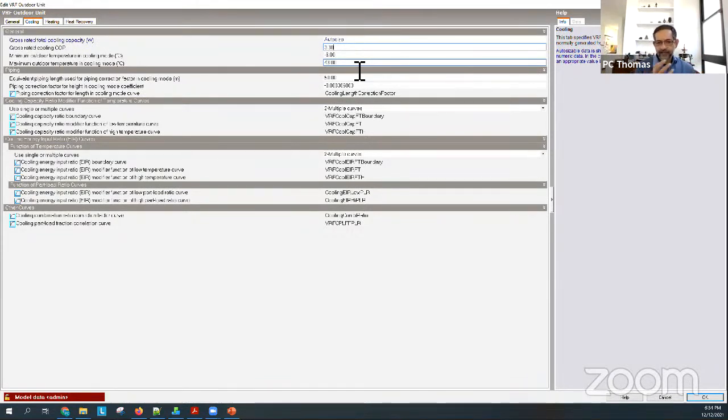So you need to find systems which will work at that design condition, because otherwise some of these systems will actually stop working because of what we call head pressure. The compressor will say it's too much load, I can't work, and then it'll just fail. Now, it doesn't happen in chilled water systems. Systems don't fail, they become less efficient, but they still provide some cooling. Even if you are at 46 or 50 degrees, a chiller will still continue to work. A water-cooled chiller will still continue to work.